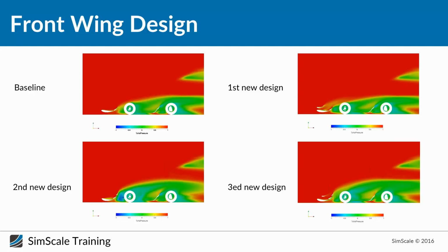So you want the diffuser to work harder than the front wing if you can, as long as your car remains balanced, as long as effectively you are close to your aerodynamic balance target of 45%, for example, at the front and 55% at the rear. So depending on the balance you have, you know if you need to work your front wing harder or less hard. So it's a little bit of a balancing act.